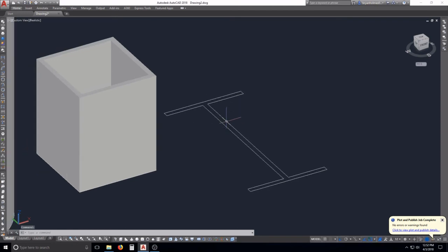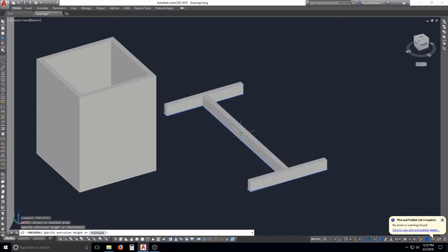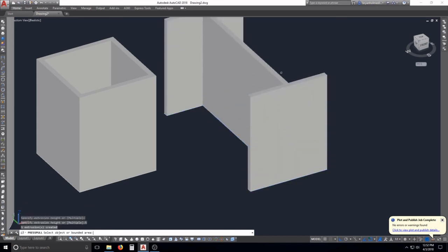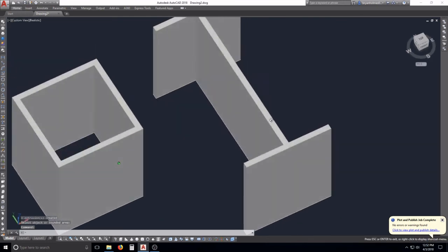But anyway, so we can press pull this up real quick. So it's PRESS. We don't have to do anything fancy with it. And type in 5, and there you go. Look at that, guys, and that is a solid piece.